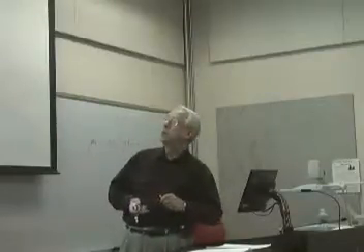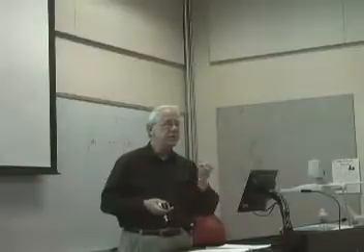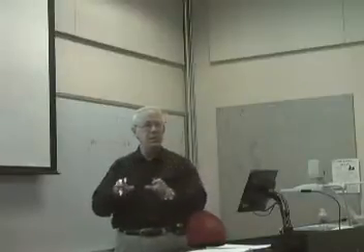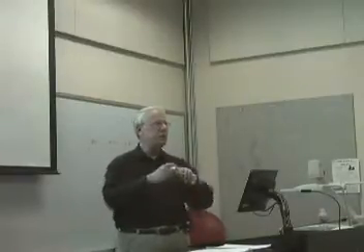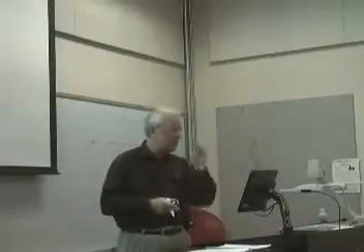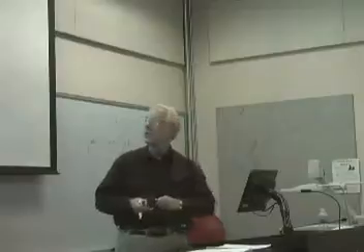What you wind up with are the shape functions are now defined in terms of these non-dimensional values. And they're easy to solve. So remember, you're doing this element by element. So you do the transformation on the fly. So you do it every element as you go through. So you don't have to do a global transformation to try and make everything look like a box. You only do it element by element.